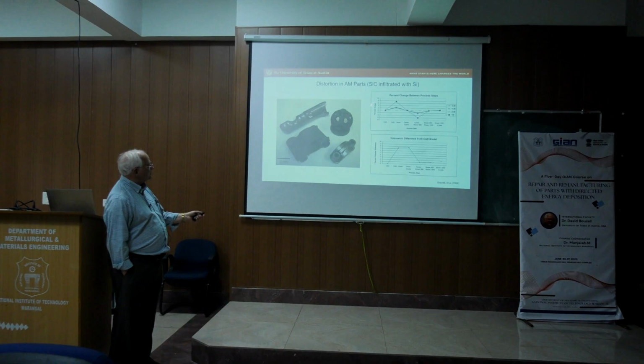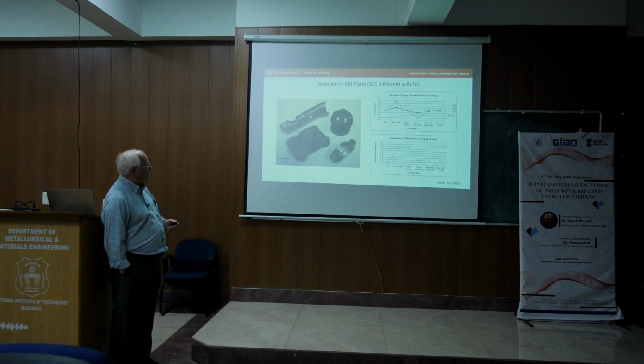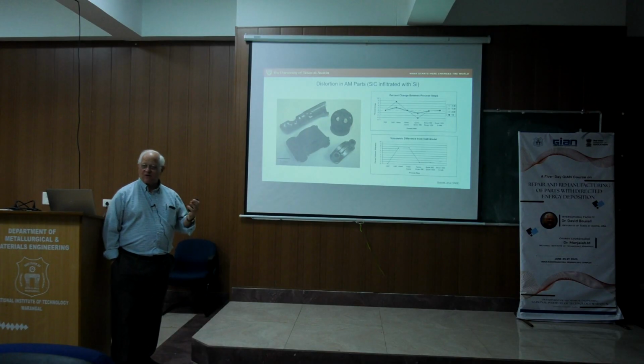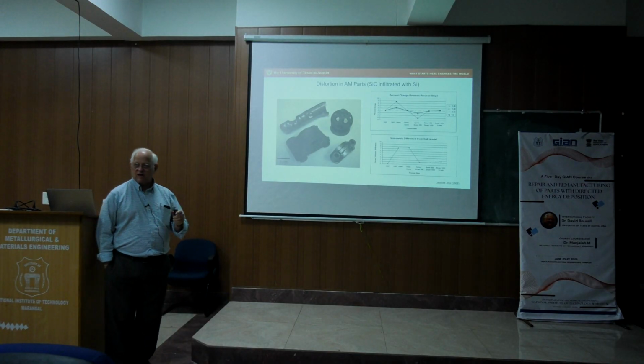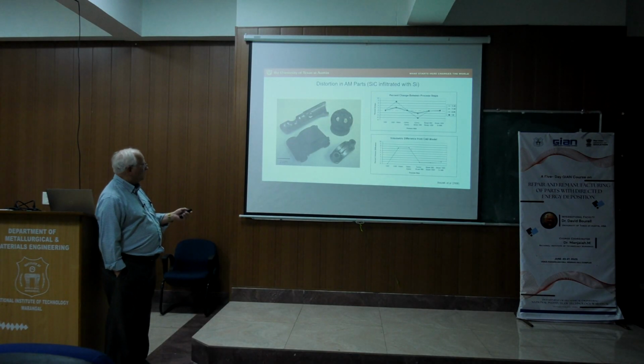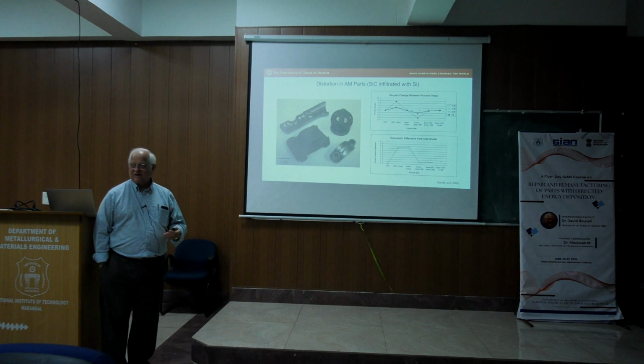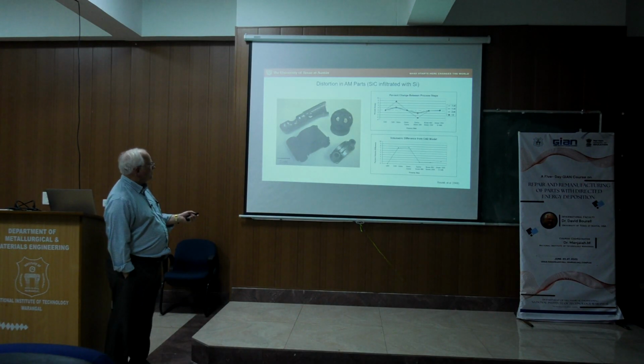This is the percent change in the distortion, I would say, the expansion or the contraction. It's the linear change in the dimension in percent. So this is 0, 10%, negative 8%. And so 0 is basically the solid model, the CAD.